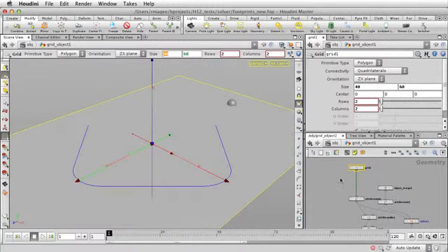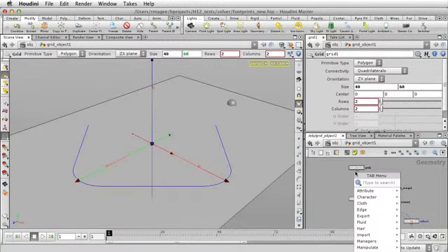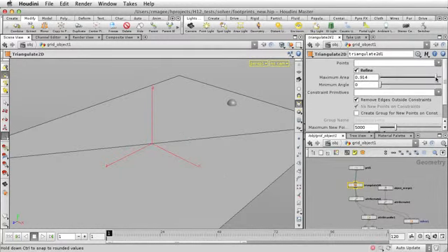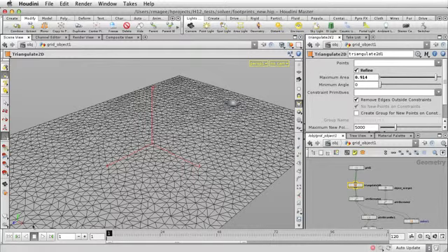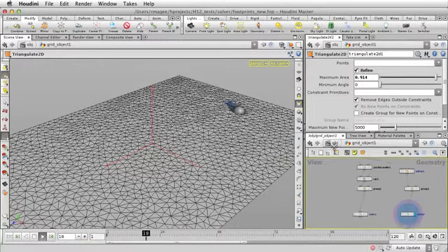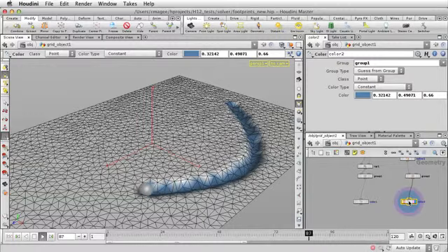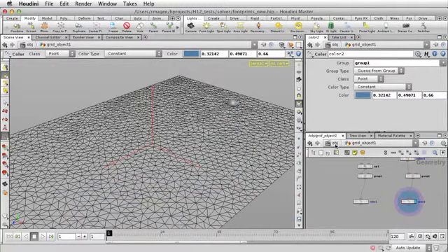2 grid. We're then going to put down a triangulate 2D. This node will allow us to create a different kind of breakdown of the surface. And now as we go through there, you'll see that, well, actually we should put the display on the final color node. You'll see that the trough is a little bit more organic, and if you put a subdivide on this afterwards, it actually looks quite nice, and will certainly look like an object pushing its way through the snow. So there we've got the basic functioning parts of our snow tool ready to go.